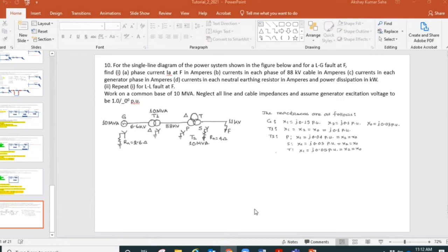I'm not sure if I could explain it properly, but when we have this composite waveform, it's not a single waveform that we work with coming out of the generator of 50 Hertz. It's a composite waveform. It has multiple frequencies in it, and if we do the Fourier transformation, we will know what frequencies are present. We will also know how much of each frequency is contributing to that composite waveform, like 99% fundamental frequency, 0.2% for one, and all the others making 1% together.